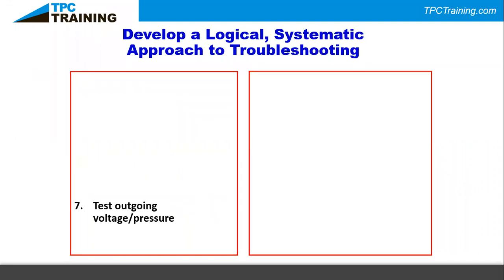And then from there, what do you do? Well, if we know it was there at the beginning and it wasn't there at the end, whether it be the voltage we're looking for or the pressure we're looking for in the case of, let's say, water flowing or a pneumatic or hydraulic system, then we start in the middle. We basically try to split the whole system, based on what we're seeing in the schematic, into workable pieces. One smart way is just cutting it directly in half. Start somewhere in the middle and see if you get what you'd expect in the middle, and then if that's working, now you have it cut into that first half of the circuit versus the second half.